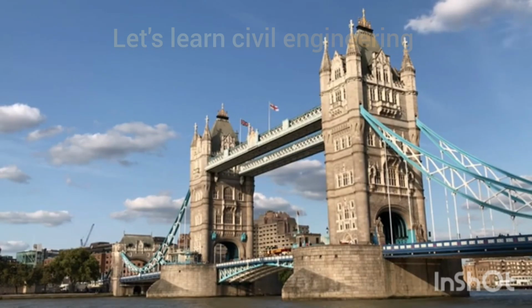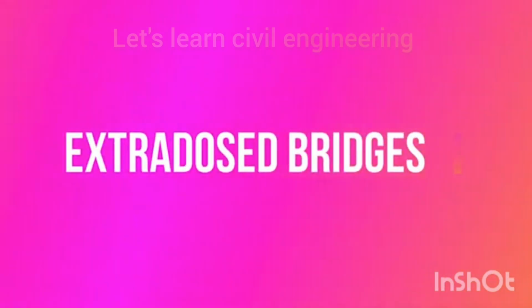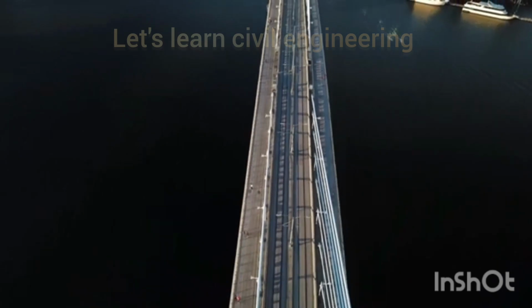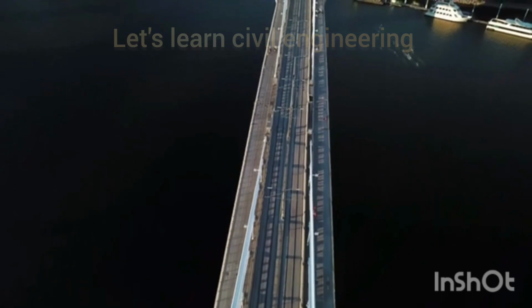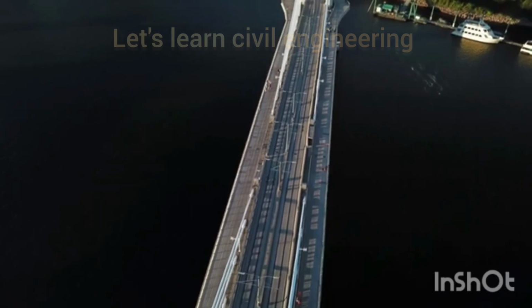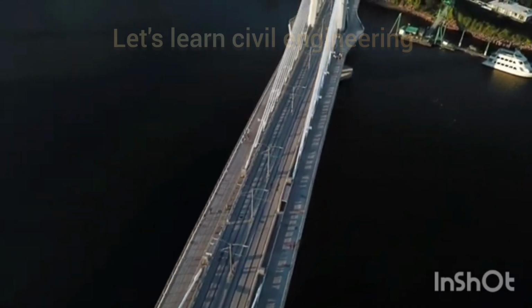Combination bridges. These bridges are a combination of a girder bridge and any one of the aforementioned bridge types. For example, extradosed bridges. The extradosed bridge is a special subset of the cable-supported girder bridge. Extradosed originated from a French word, which means top fiber. Extradosed means that pre-stressing tendons are passing above the top fiber, thus the function of the extradosed cables is also to pre-stress the deck, not only to provide vertical support as in a cable-stayed bridge.